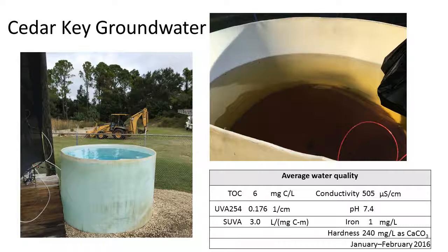So they add permanganate at the well. It goes to a magnetic ion exchange process for DOC removal, and then lime softening for hardness removal, and then sand filters with chlorine. And they add the permanganate because they were getting fouling of their existing ion exchange process with the iron. And so they try to get all the iron oxidized before it gets to the plant. The well field, there's 2 wells that they switch between. The well field is a few miles away from the water plant. I can remember, maybe 3 miles. So the water travels about 3 miles in the transmission main to the water plant, and they like to try and get all the iron oxidized because of the problems they've had with MIEX.